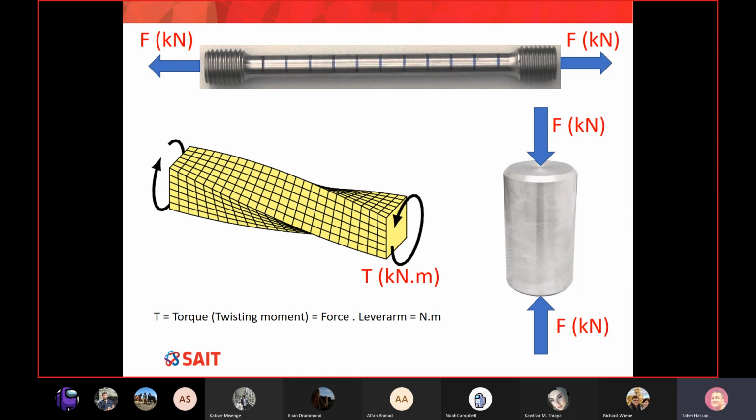And really, I want to emphasize a couple of things. Number one, in this case, there will be two kinds of stresses. And one stress is a shear stress, and shear is not normal. Normal stress is perpendicular to the cross section, while shear is in the same plane of the cross section. So the stress is parallel to the cross section, not perpendicular. Also, along the longitudinal fibers of the specimen, you will also see some tension.